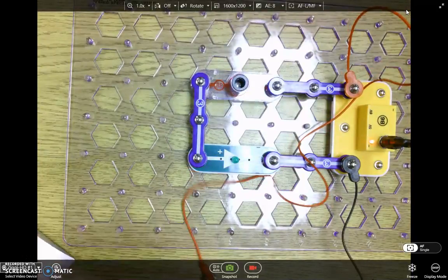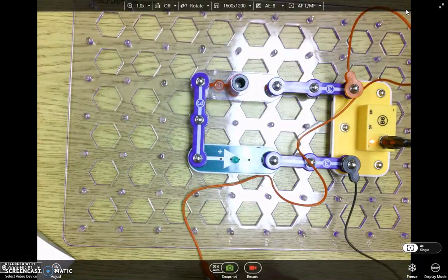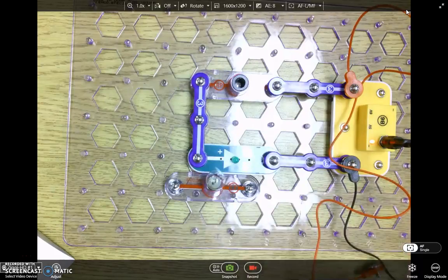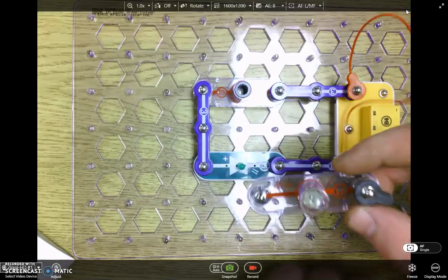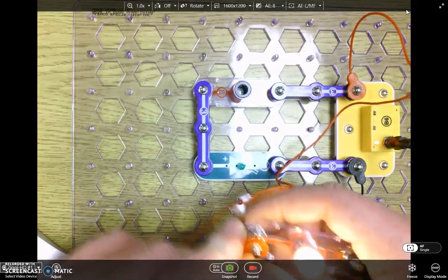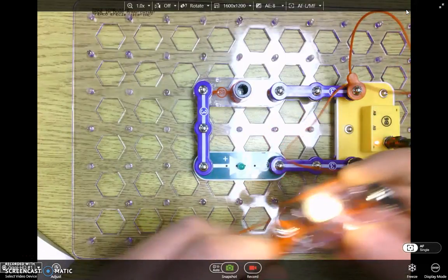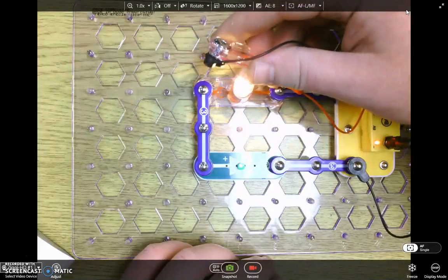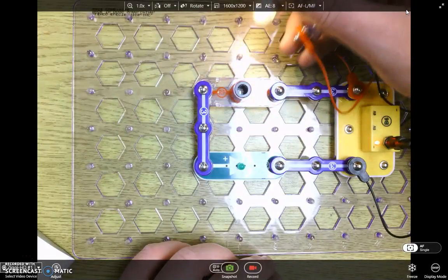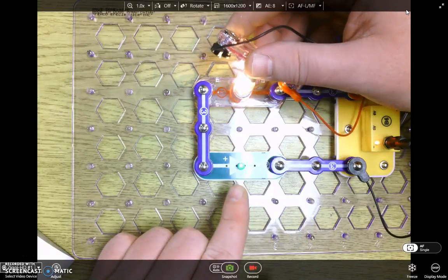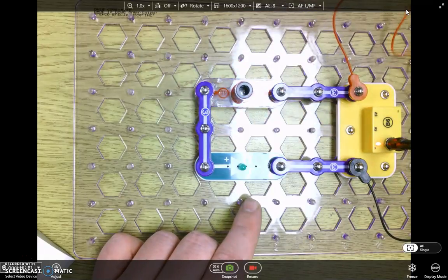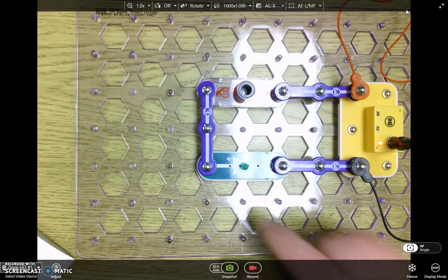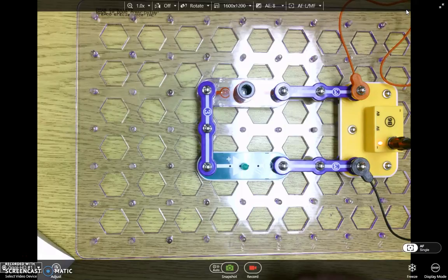Now, the ends of them you're going to plug in to either side of a light bulb. And you don't have to have this thing hooked to the board. So we're going to plug these in just like so, and that lights up. Then when you take it over your photoresistor, you should get that LED to light up when the light is in front of it. Now I want you to see what else, once again, this works with. See if you can swap out this LED for something like a buzzer or a motor, etc.